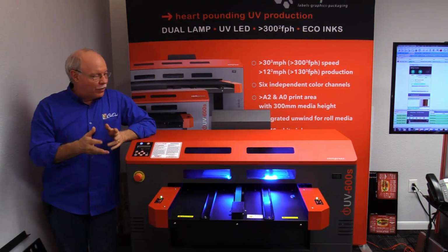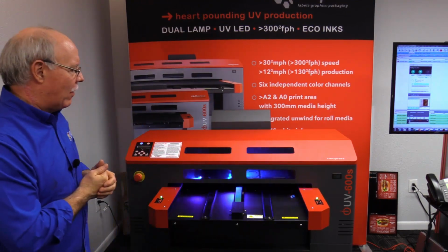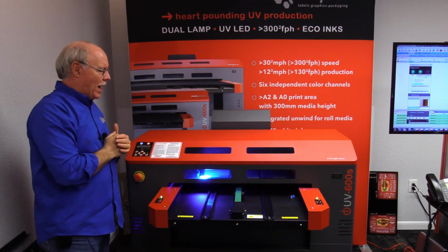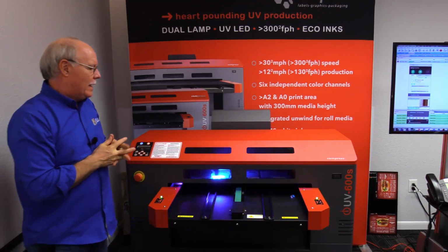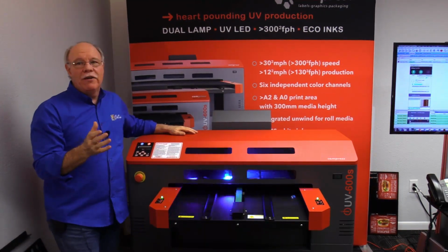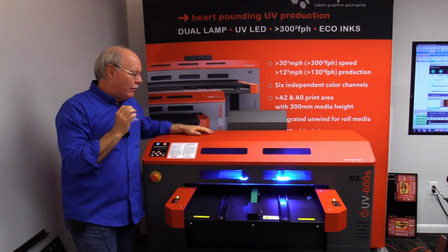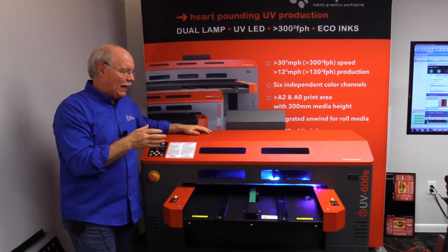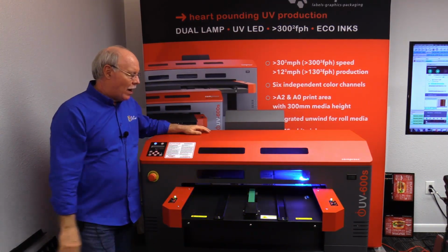All right, as you can see, the printer is starting to run here. We sent this over. This is what we call our production mode, which is bidirectional, which means we're printing both directions, left and right, as we advance the bed. And it's a bidirectional 720 by 720 DPI print, which we find for the most part is excellent for this type of printing that we're doing. There's no reason to get carried away and go deeper than that unless you have some really high detail, especially on something like cell phone cases. So that's what we're doing right now, we're printing those out.